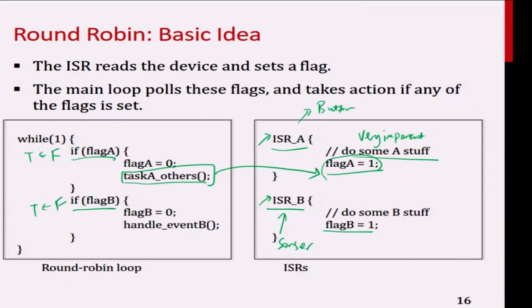The important thing is what? The data that is coming in, the information that is coming in, I must capture first. Correct? The processing of the data can be done later. The data is important. The processing can always be done later. So the very important thing that I need to do inside the interrupt service routine is to capture the data.